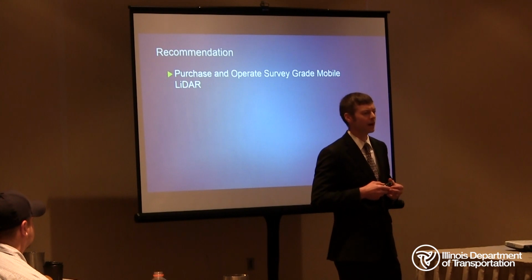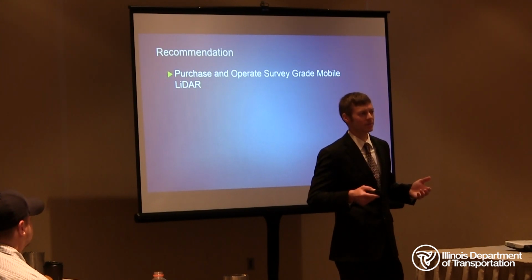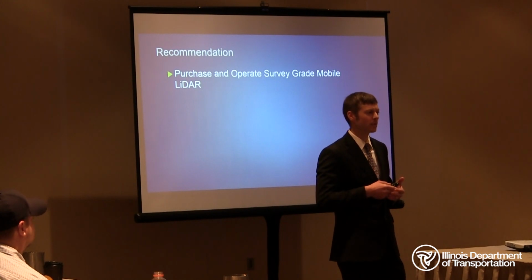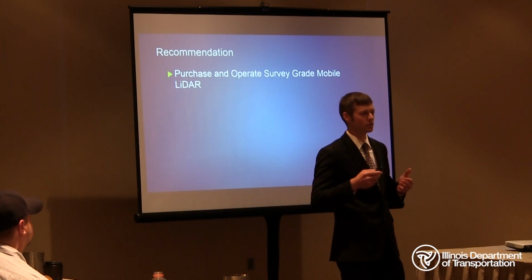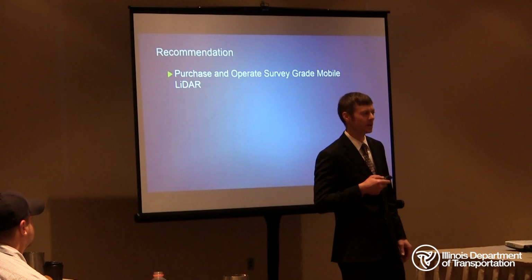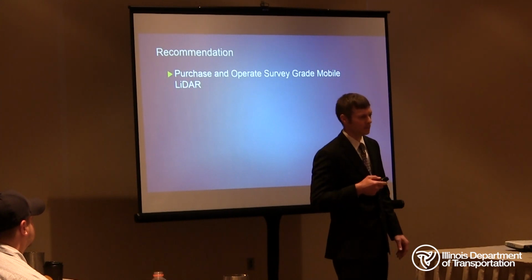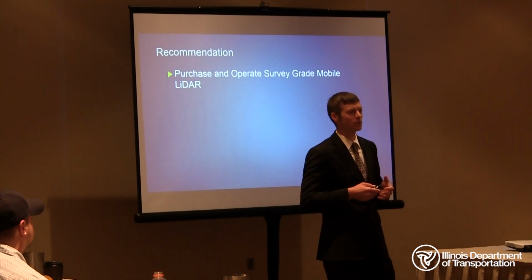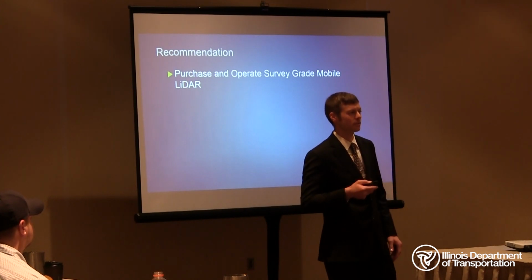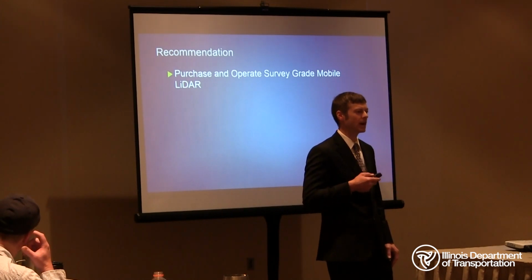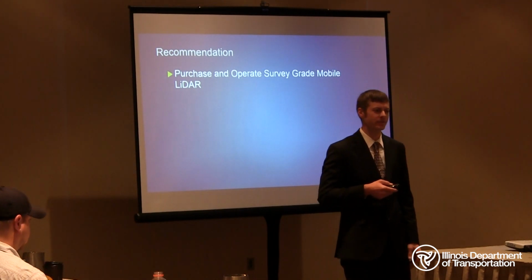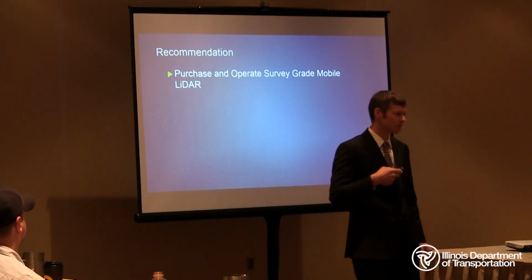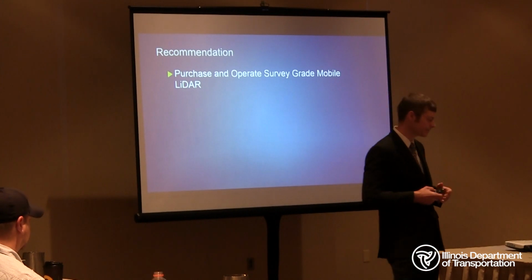Also, in regards to aerial mapping, mobile LIDAR acquisition can occur during all times of the year, where aerial mapping products typically only occur during 2 small windows, one being in the spring and one in the fall. And with the availability of countywide aerial LIDAR, more districts are beginning to use that information for ground contouring and are seeing a higher need for mobile LIDAR pavement surveys, contrary to photogrammetry products.